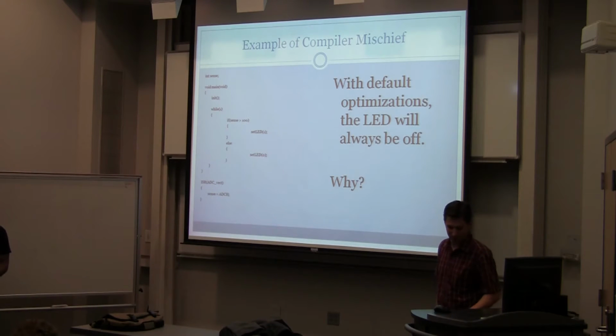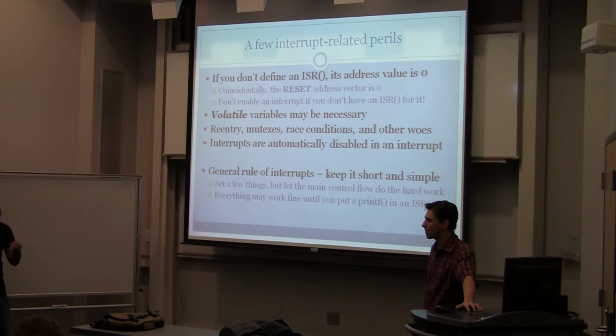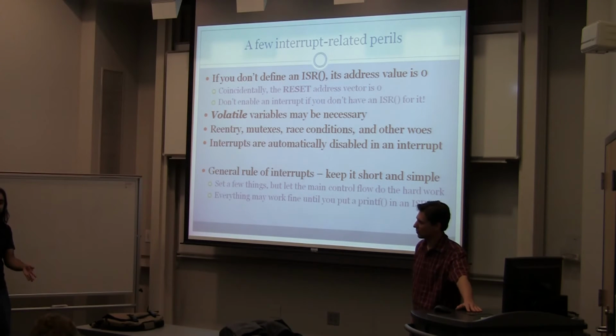Why would anything happen? Well, the issue is that you don't know when these things are on hold, and you don't know if something else wants to interrupt as well. So think about if you had, say, 2 timers running, and you wanted one to trigger every 100 hertz, and another to trigger every 200 hertz. But the 100 hertz function takes like a second to compute. Basically what's going to happen is that first one's going to hit, your main function's not running, the interrupt's not going to get called again because it's already being serviced, your other timer's not going to get called again because this one's being serviced. And so now all of those have been delayed, and that can cause issues.